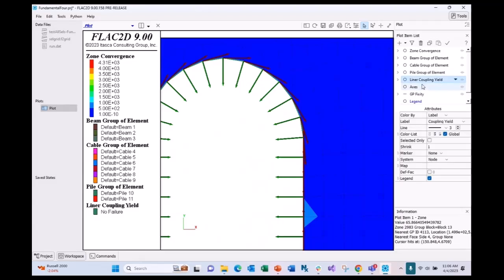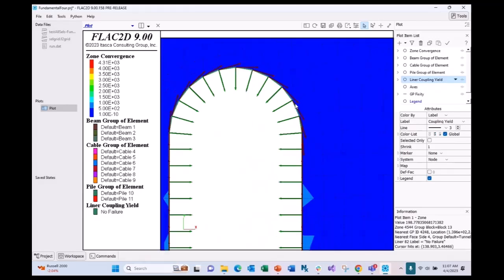Structural elements have their own local coordinate system. This is important when assigning a load or a velocity to your structural element. You actually do not use the global coordinate system, which is shown right here, y-x. You use the local coordinate system. The local coordinate system will always be generated automatically for you.